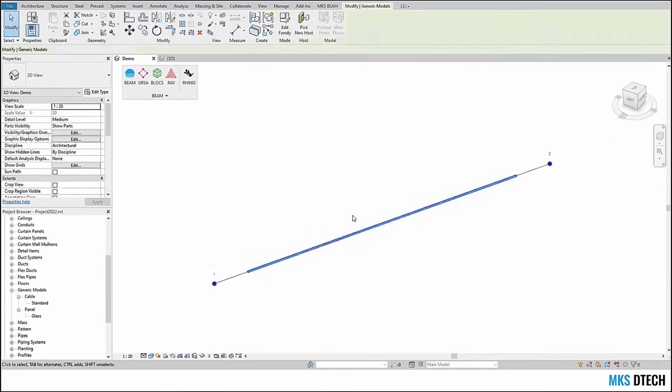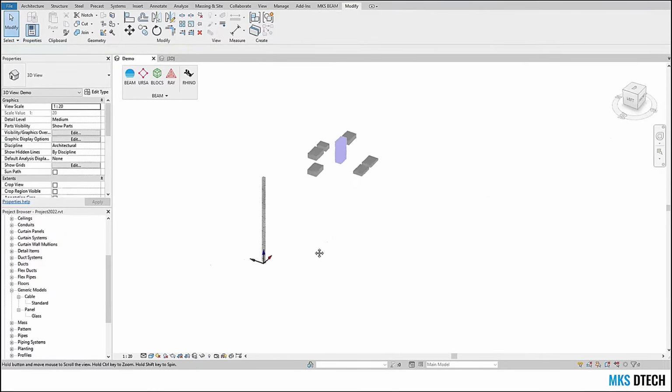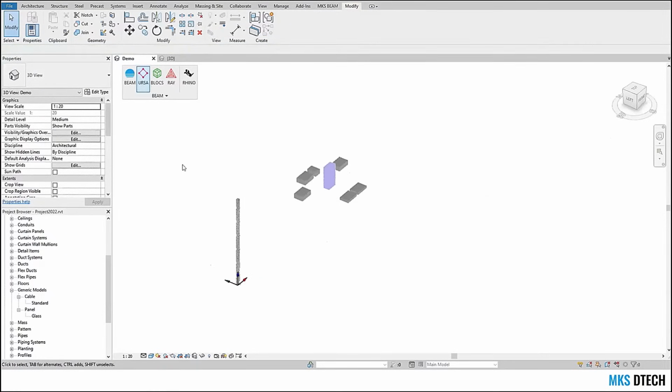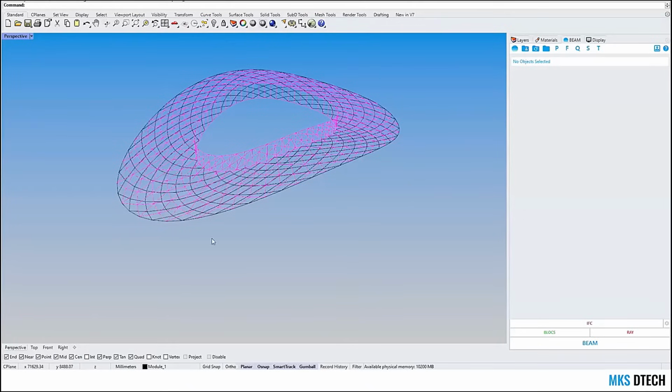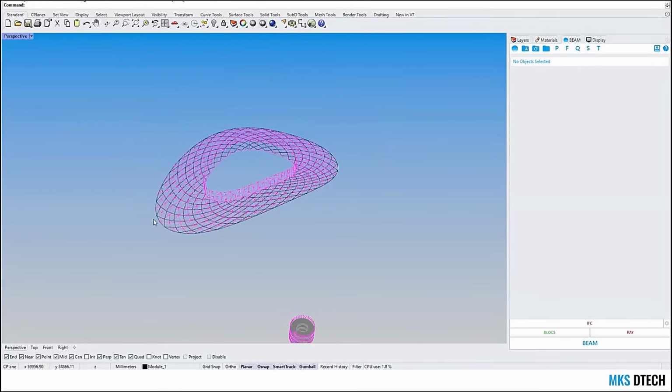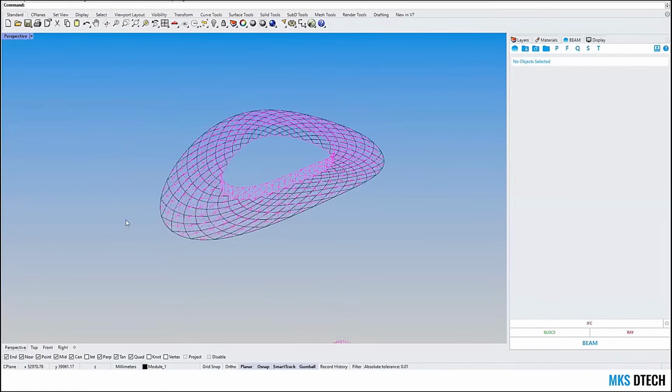So what we're going to learn now is how to use BIM, and especially Ursa in this case, to import adaptive components based on Rhino lines. So if you open your file adaptives, it should be in the data set. If you are using Rhino 6, it's called adaptives_Rhino 6. If you're using Rhino 7, it's just adaptives.